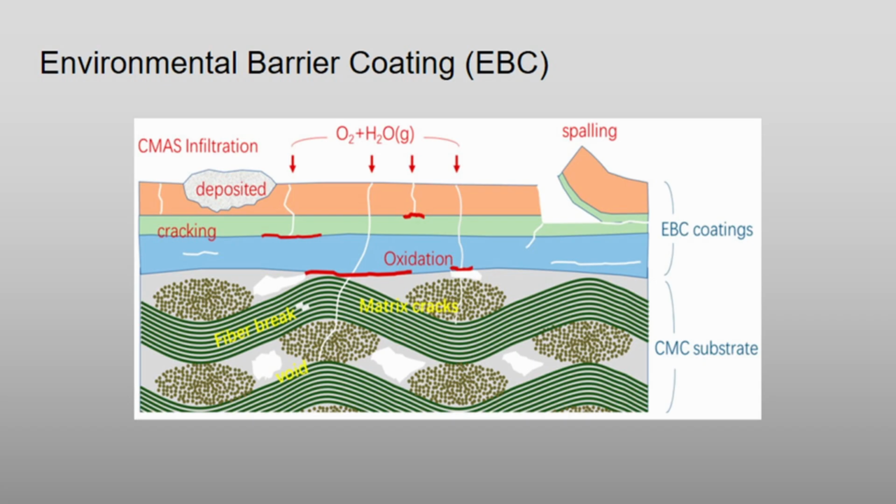Environmental barrier coating (EBC). In many turbine applications, a final protective layer of rare earth silicates is plasma sprayed onto the exterior to protect the finished ceramic from high temperature water vapor degradation in flight. The microscopic cross-section illustrates how a multi-layer protective coating bonds to the underlying matrix substrate to stop moisture-induced structural recession.